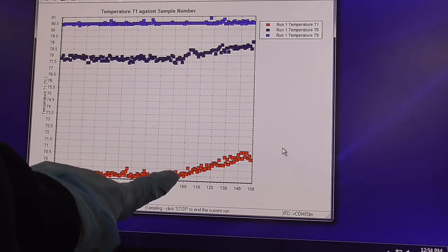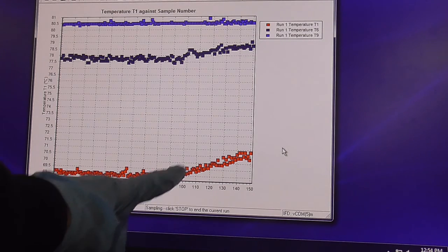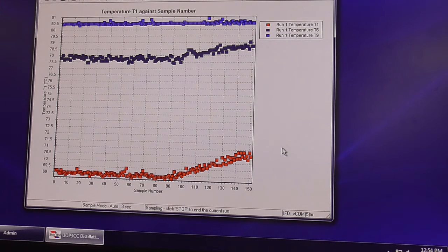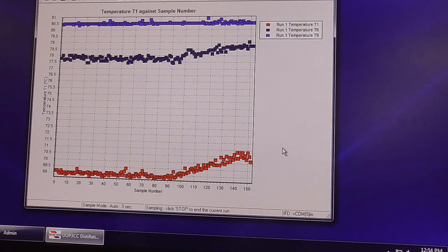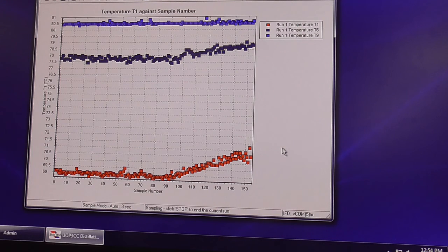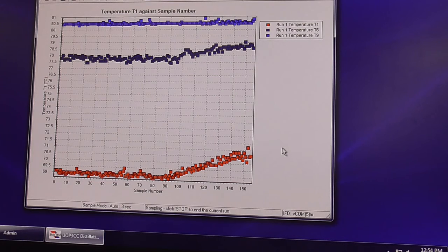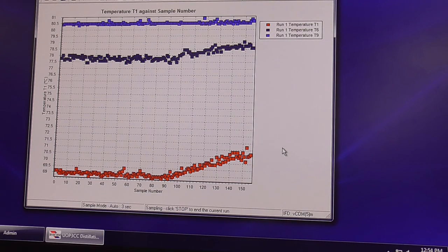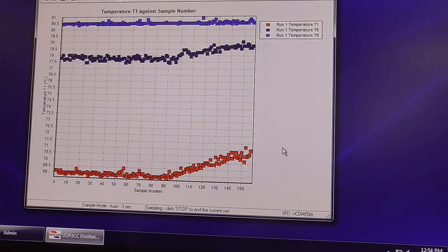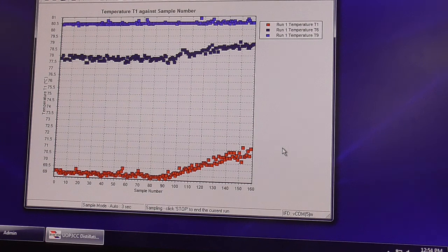You can see here on the temperature plot where I started the reflux. On T1, the temperature goes up because now I'm not sending as much reflux back as I did in full reflux, so the tray heats up. This tray is where the feed started, so whereas it heats up some from less reflux coming back on the column, it also has cooler feed hitting that tray, so it also heats up some, but not as much as tray T1.